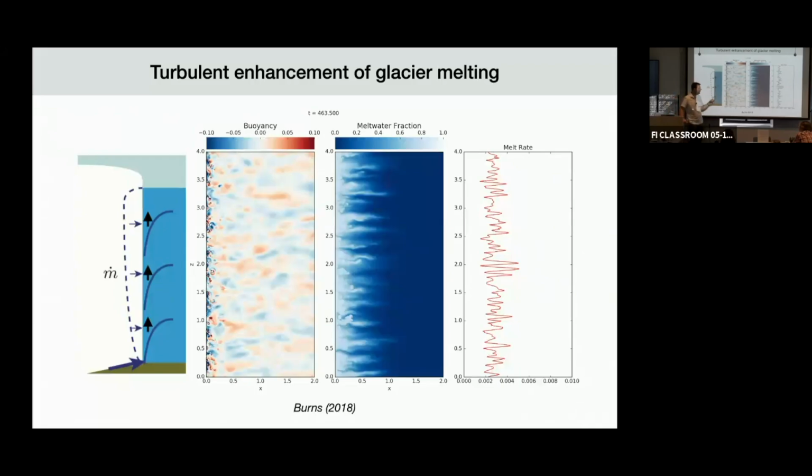Also, in some cases with a zoom-in simulation, maybe you do only want to simulate a parcel of a fluid, but if there's a large scale inhomogeneity, like a background stratification or something like that, that may also break the periodicity, right? So you might say, I want a segment of the atmosphere at a certain level, and that's very different than the atmosphere far above and below. So maybe in some cases, doing a periodic boundary condition vertically would be bad.